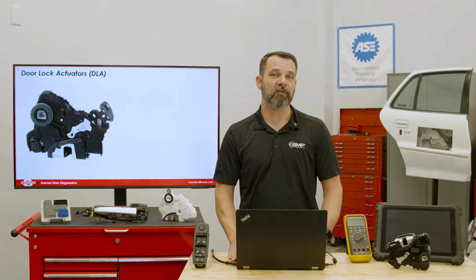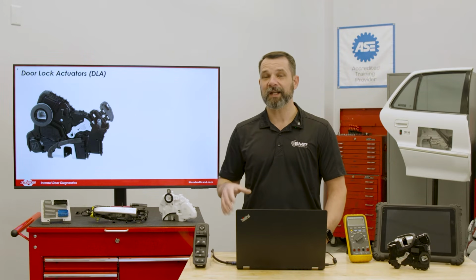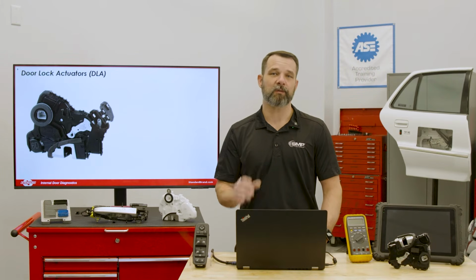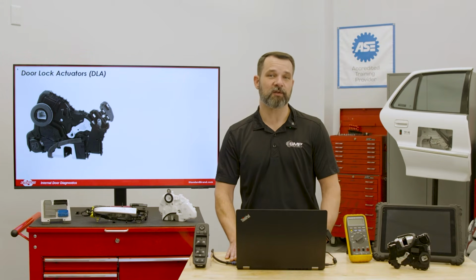Now, most of these modern actuators are actually integrated into the door latch assembly, so keep in mind, in the event of a failure, you're not just replacing the motor, you're actually replacing the latch mechanism and the motor as one complete unit. Now, we do have some fairly common failure points with these door lock actuators.